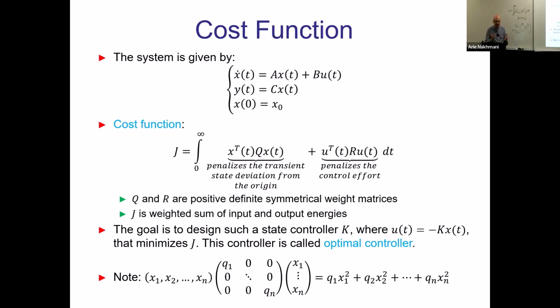So you know what these things are, right? Because you designed the system. So you know how strong or high your values should be. What are your physical limits on your system, right? So you're saying, for example, u is too strong. What should you do? You bump up the R, right? So try a stronger R, simulating the system until it gets to a normal level where it needs to be, okay? So it's easy to play with that number.